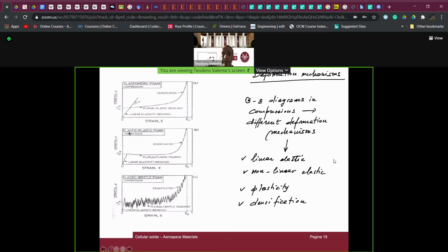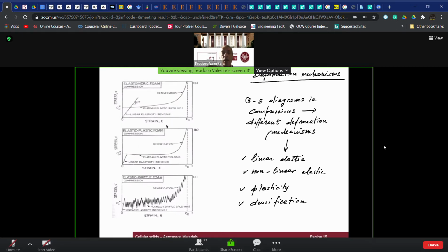And in this case, what we can expect is related to the first part of the behavior, which is always the same, because it expresses, let me say qualitatively, not numerically, the linear elastic response of the materials, unless we reach the limit for buckling, or, as it always happens, the limit of plastic yielding of the materials itself.